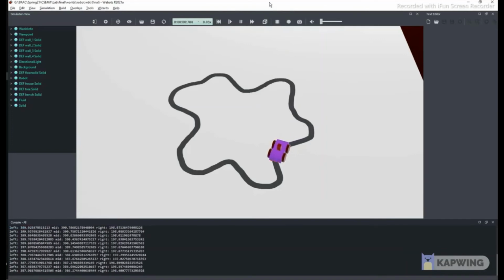We hit play. Okay. So as we can see, it's running smoothly. The way this works is during making left turns, the left sensor and the middle sensor will give a high reading, whereas the right sensor will give a low reading. This difference causes the left motor to stop temporarily and the right motor to speed up temporarily. This causes the bot to make a left turn.